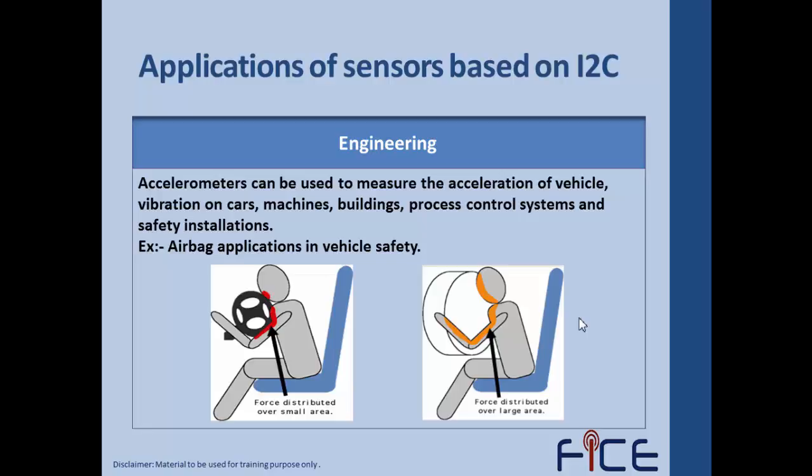During a crash event, the vehicle's crash sensor provides crucial information to the airbag electronic controller unit. Once it receives the information from these sensors, the airbag electronic controller unit determines if the crash event meets the criteria for deployment and triggers the various firing circuits to deploy airbag modules within the vehicle.